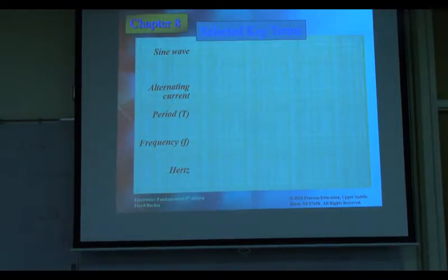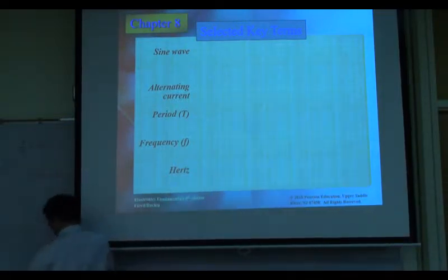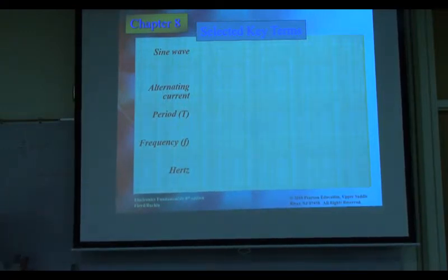What's the difference between a sine wave inverter and a pure sine wave inverter? Pure, P-U-R-E, pure sine wave inverter. Okay, pure sine wave means it's a perfectly sinusoidal function. Let me explain this. Because I know, for example, if you hook a microwave up to a sine wave inverter, it'll have issues, but if you hook it up to a pure sine wave inverter, it'll be fine. You want to use this one. And there's another name. This pure is compared with... anyone knows? Pseudo sine wave, right?